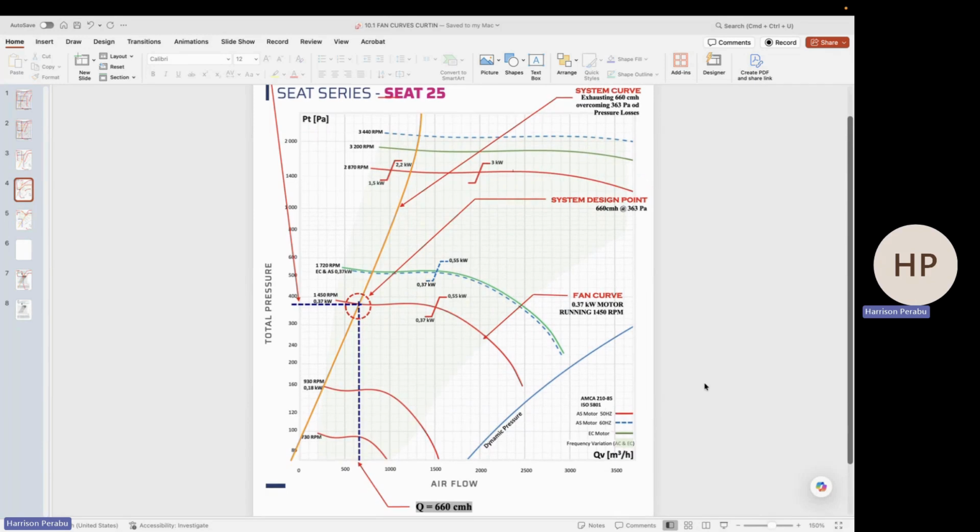It's one of the most commonly used in Malaysia, at least, mainly because of its price structure and it's easily available. And somehow or other, the range of the fan easily works for typical laboratory components, the type of hood, which is the heart of a ventilation system. Hood is basically the geometrical shape which is used to effectively capture contaminant at the local point of generation.